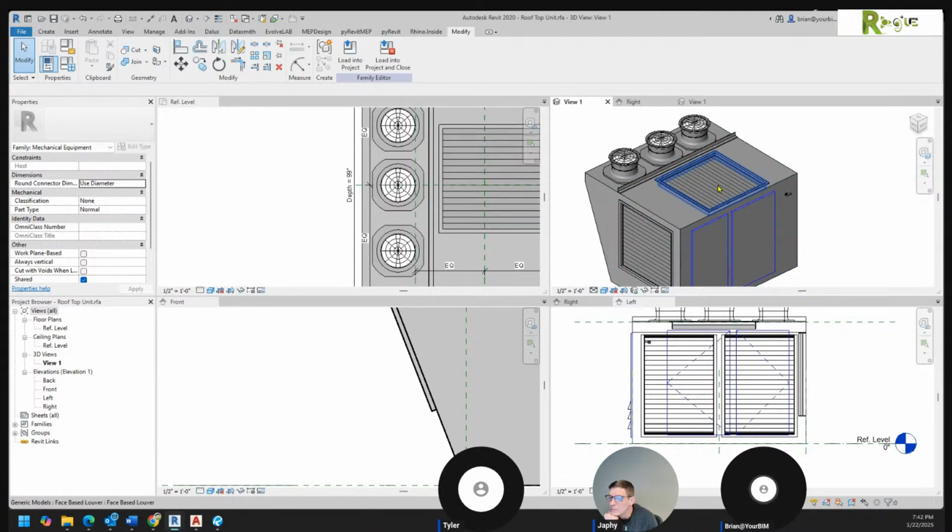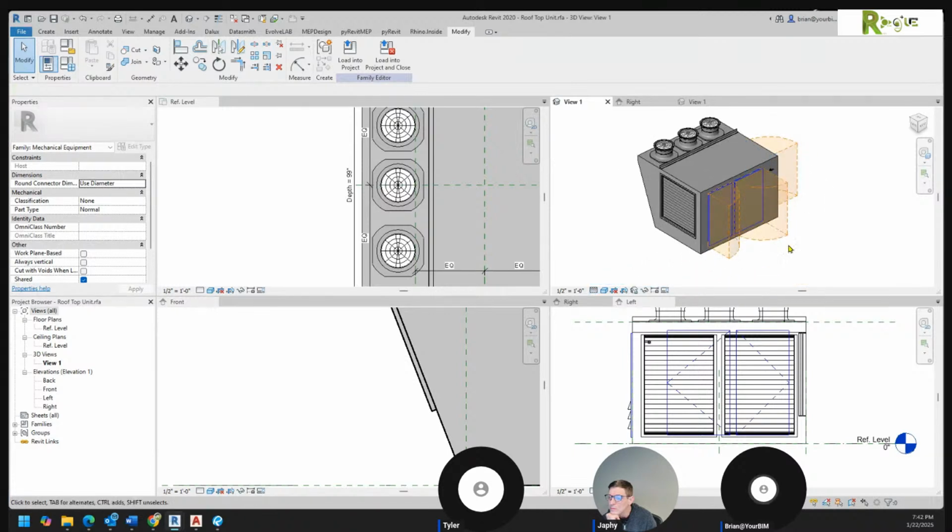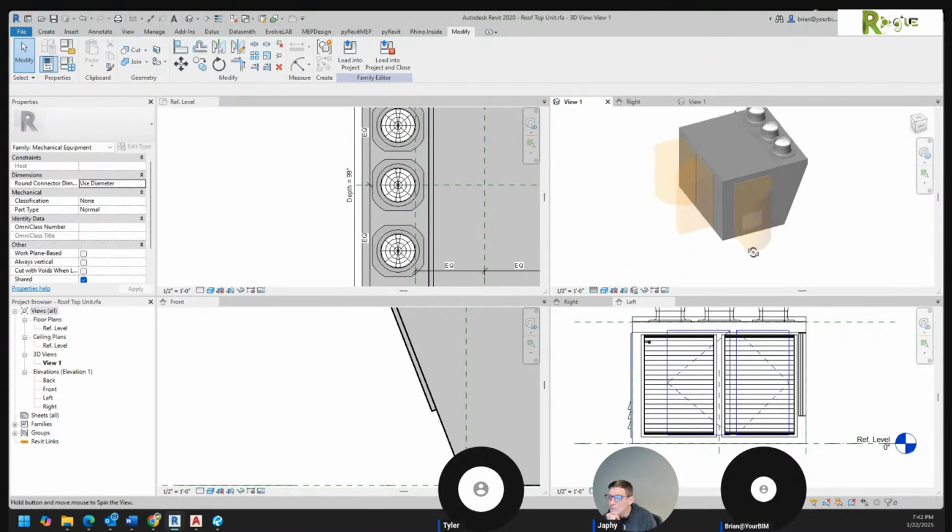But the idea is, number two, in fine mode, all of my doors actually have door swings on them. So the person can see those doors have got to be able to open. Don't put a window washing bollard on top of the tower right next to that unit where you can't access that door. I say that from real experience.